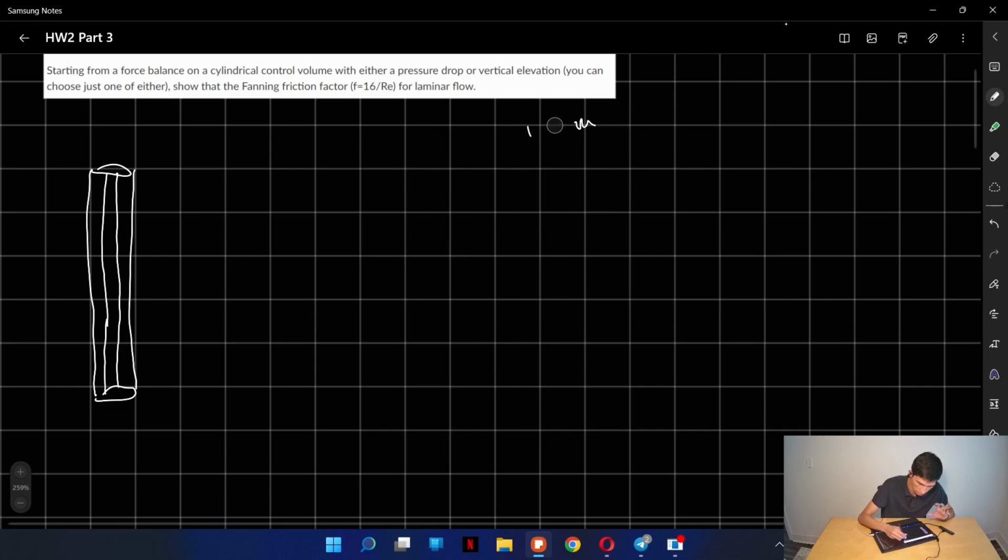So we're going to consider this tube and do a force balance for our specific case. For this case, we know that there is the weight of a liquid column, and there's also delta z, which is the height, the length of the pipe. We can say that it's a negative length because it's going from up to down. So delta z is referred to as a negative length of the pipe.